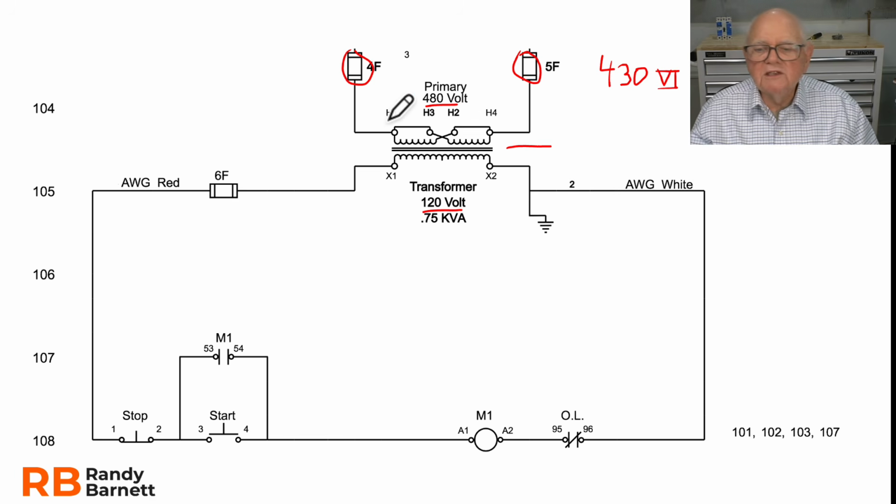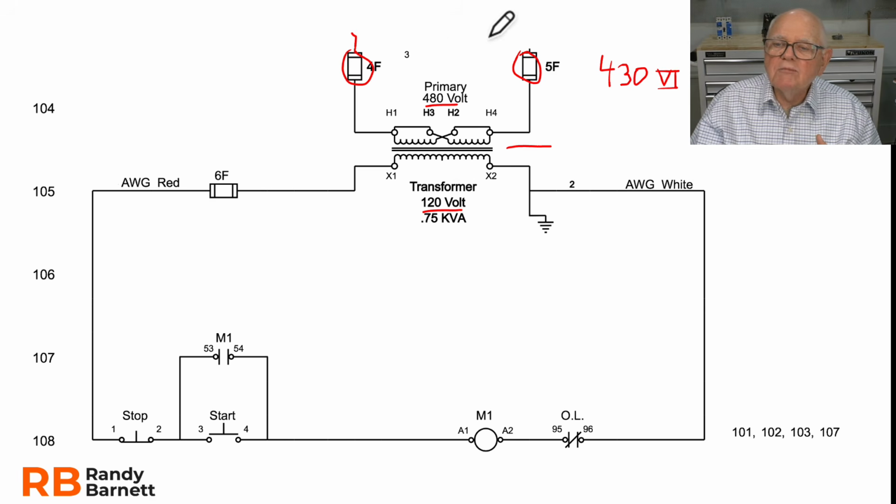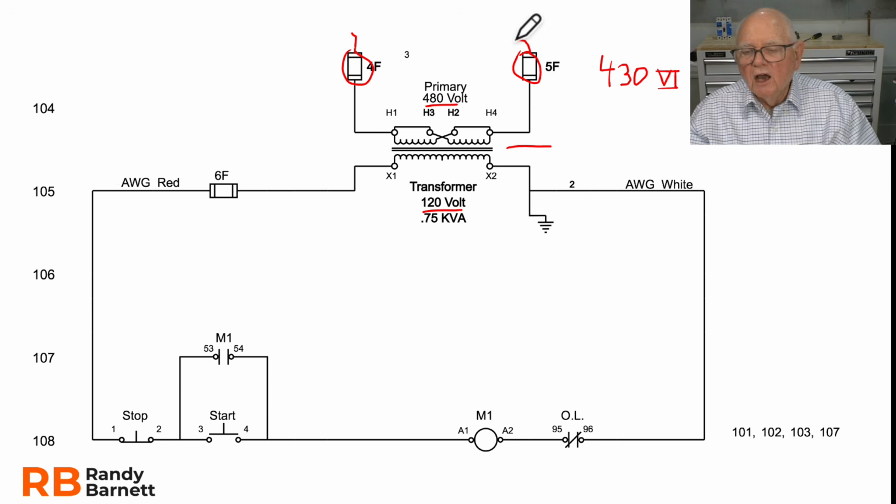It's also going to tell us things like, for instance, that if this control power transformer is located inside of the same enclosure as that fuse disconnect we just saw, say for example inside of an MCC cubicle or MCC bucket, then the control power transformer must tap off of the load side of that disconnect, short circuit, ground fault protection, in other words, the fuses that are inside of that enclosure, so that when I throw that disconnect switch to turn off power to the motor, I'm also de-energizing my control circuit at the same time.